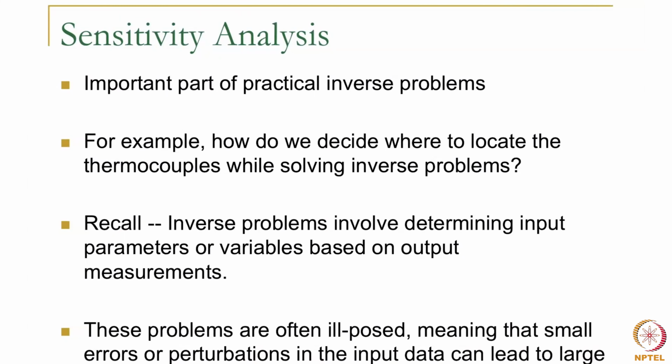So where is sensitivity analysis used? Just to give you a simple example, suppose we want to decide where to locate the thermocouples. So I had just said some standard locations, but suppose you want to do a more scientific, more analytic technique or more rigorous way of finding out where would be the best locations to keep the thermocouples so that your inverse solution is less erroneous, has fewer errors.